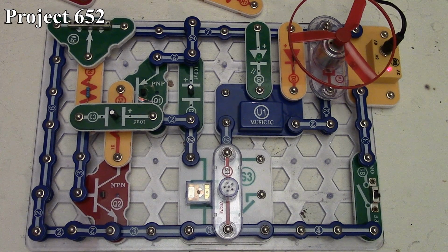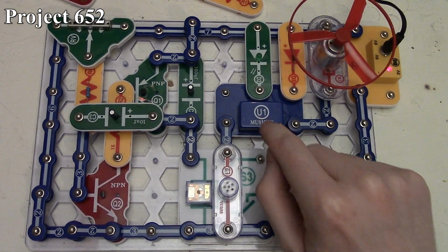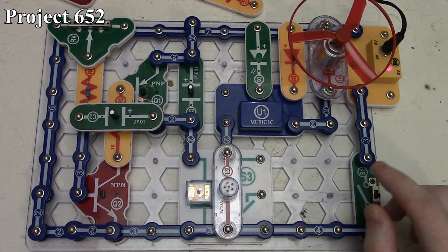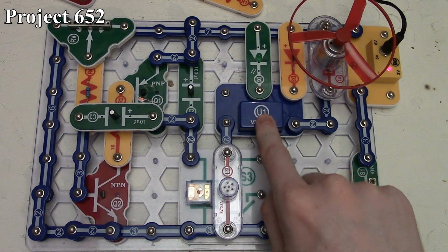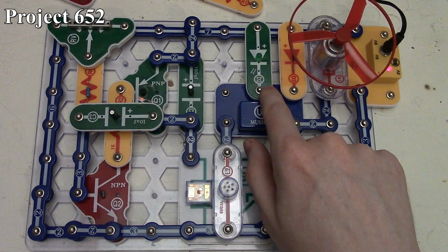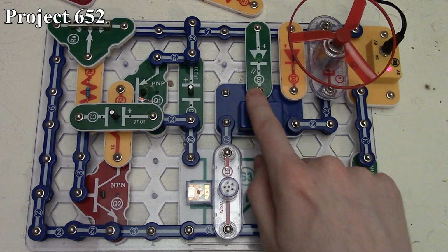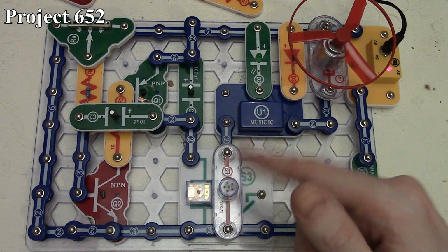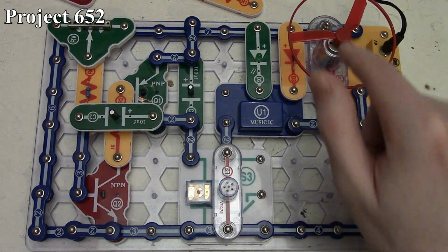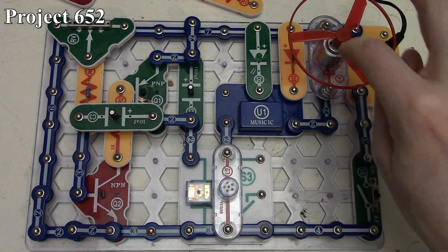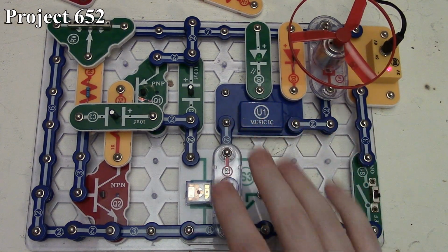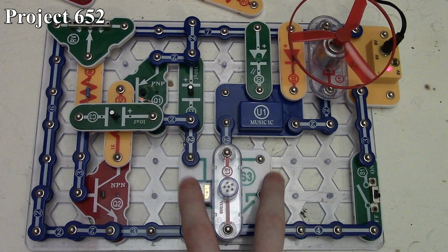So this is actually similar to a previous project, I think, where we had the alarm IC here instead of the music IC. So we've got a 6-volt supply controlled via our slide switch, which is feeding our music IC. We have our green LED here for providing the feed, and then we've got a regular D3 diode, which is connected to the hold function, so it's going to repeat. And then its output is connected to our motor with the fan attached. And then we also have power control for our music IC going through the relay here.